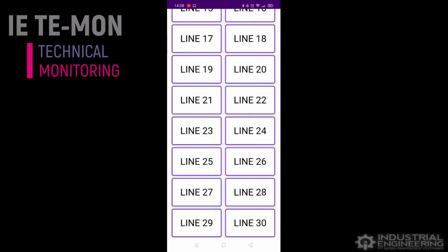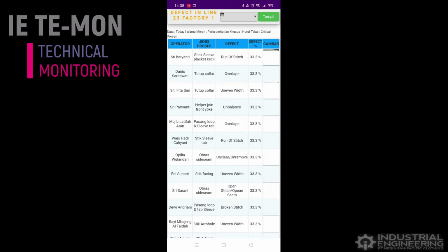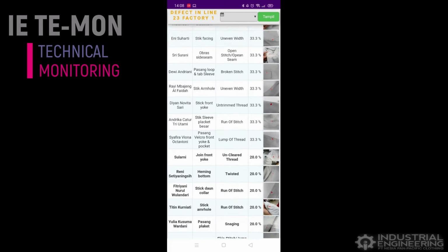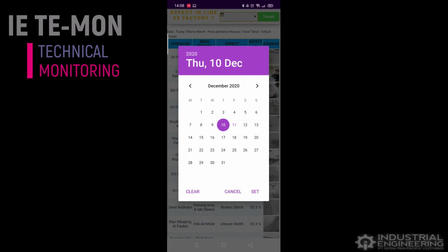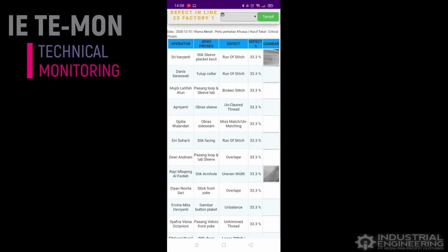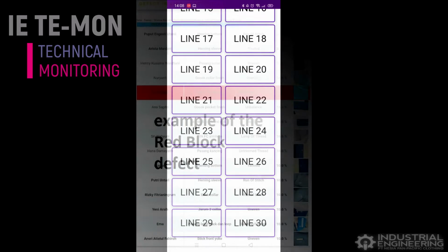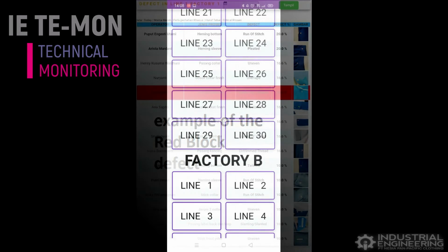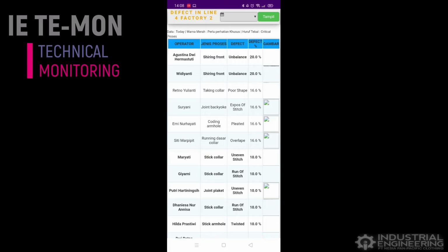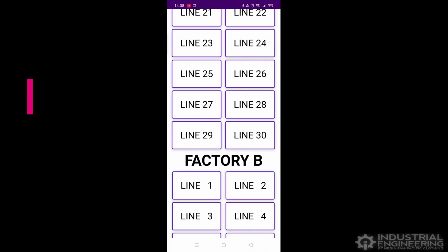Accurate means of problem solving by using quality monitoring for each process. Inline QC/mobile QC will provide real-time check results according to actual conditions. Inline defect report accompanied by a photo of defects found by inline QC with the process name and operator name. Percentage in bold is critical process and red block is process that has frequent defects more than once a day. Part checking procedure is 6 PCS for normal processes and 10 PCS for critical processes.